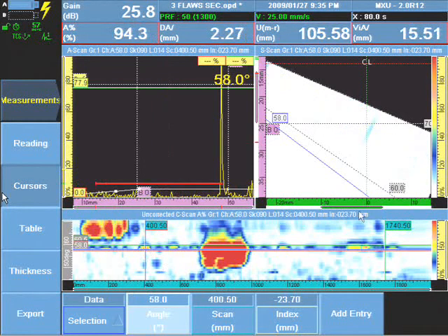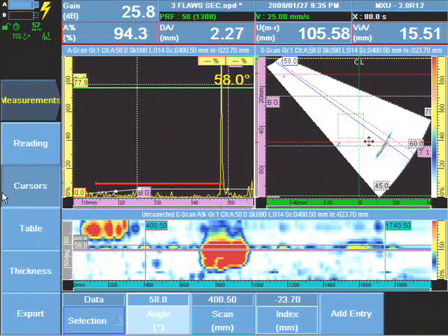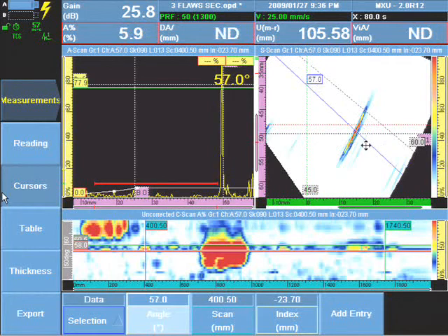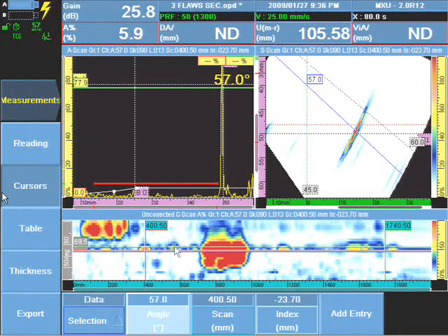Here we have an indication plotting directly to the cap on the end of our second leg. We have the first skip, B0, the end of the second skip, T1, and we have an indication very typical of cap geometry plotting right to T1. Typical throughout the C-scan.